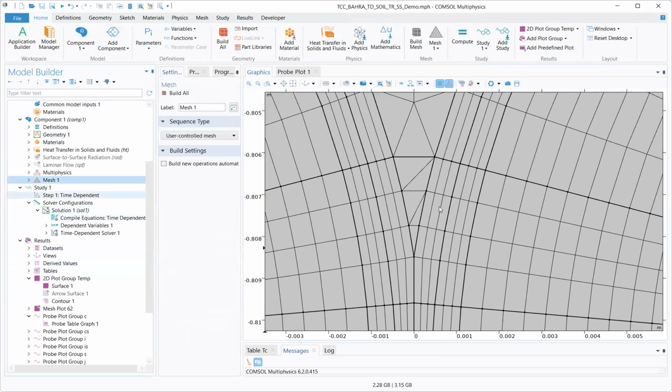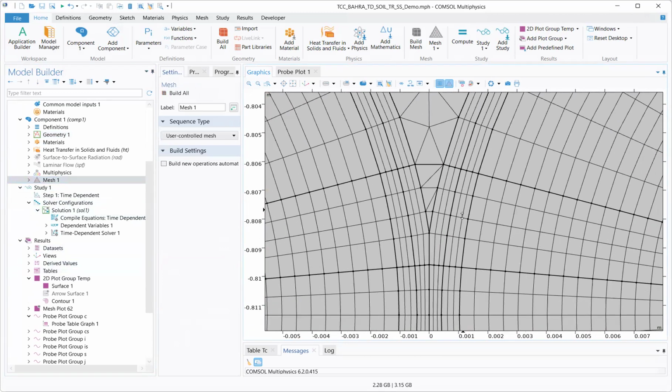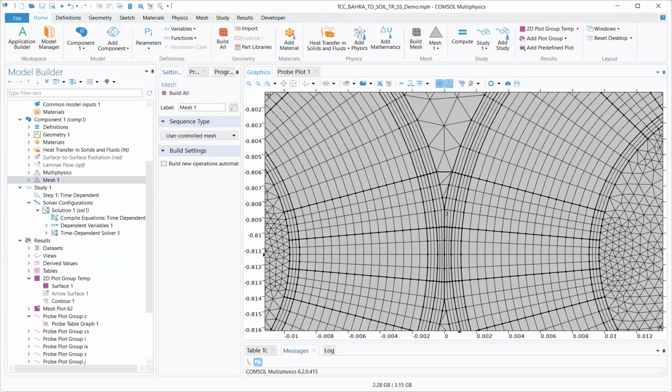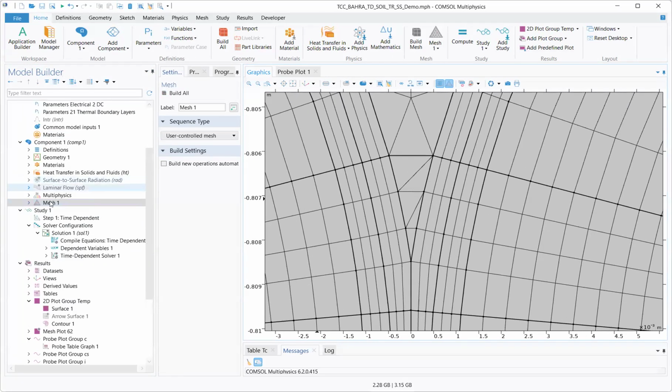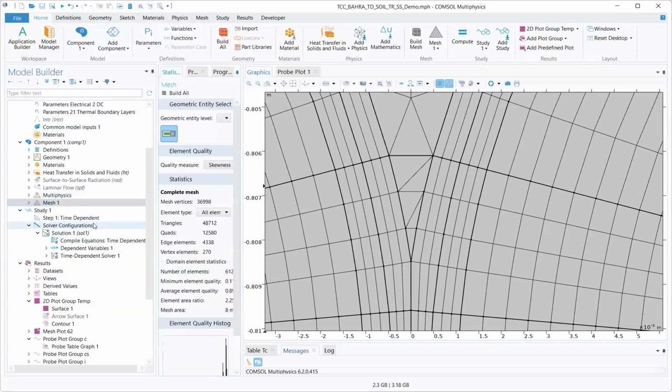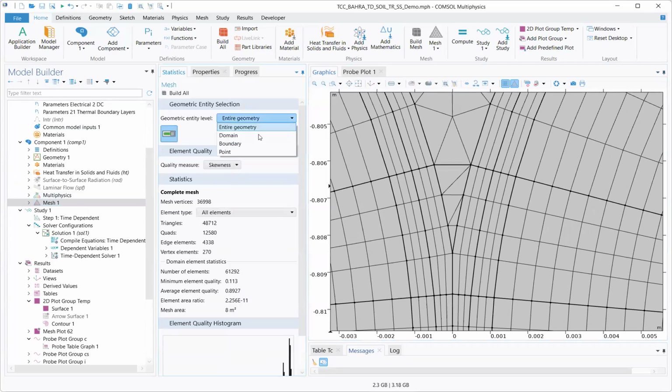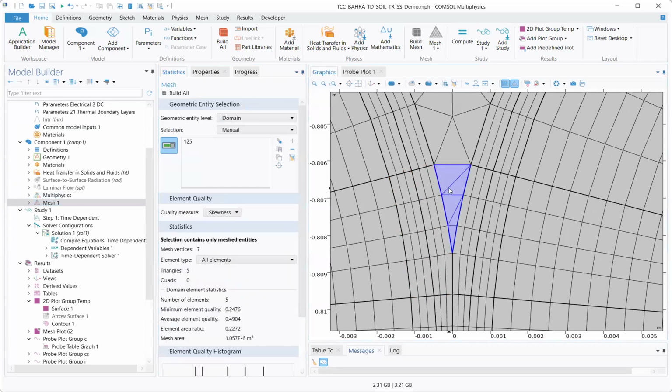The reason is that if you want to model all the way to the point where the cables make contact, at those points you're going to have degenerate triangles, and that is going to give you convergence problems to the point that the program is not going to converge. Physically speaking, two bodies don't touch each other at a point.